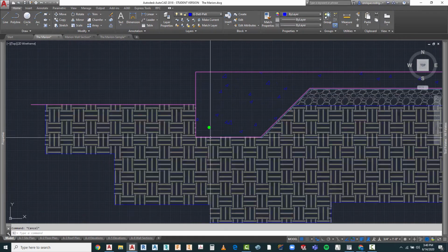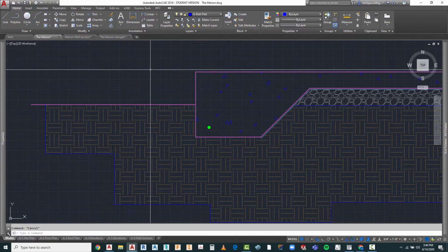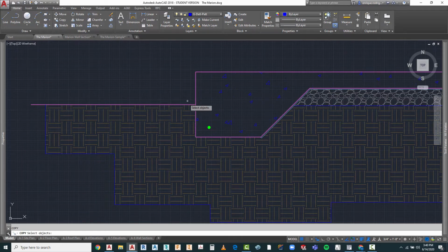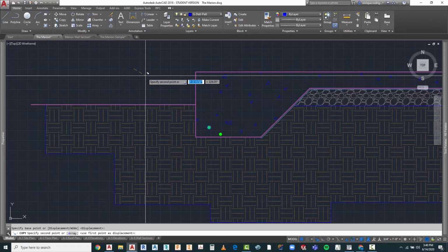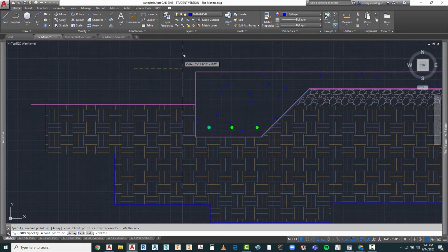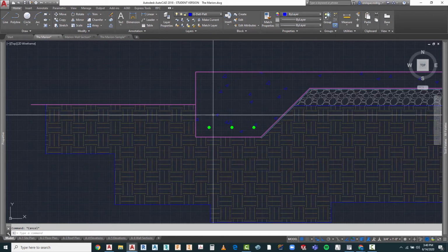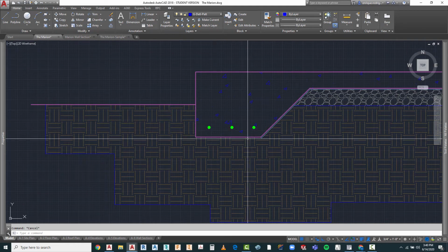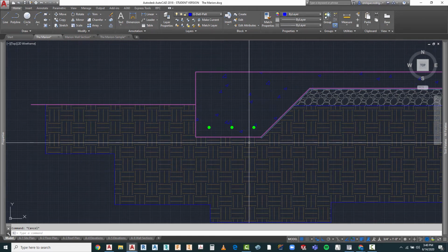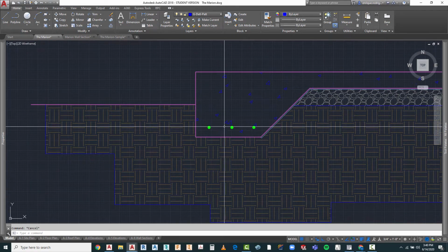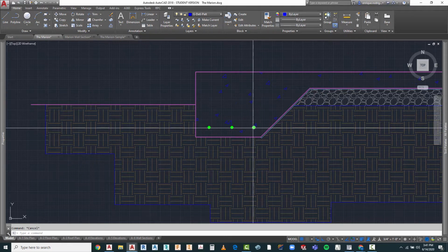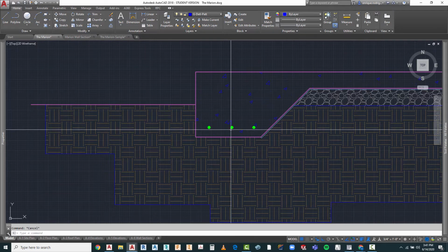This circle with the solid hatch in it, that circle is going to represent what we call reinforcing bars. And I'm going to do this with 3 bars. Again, this is going to be governed by what your structural engineer designs as a requirement based on the load, and it's also going to be based on code requirements. So what I have here is 3 bars that, if you look at them, are almost like an arrow pointing at us.